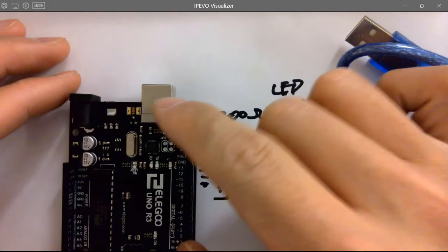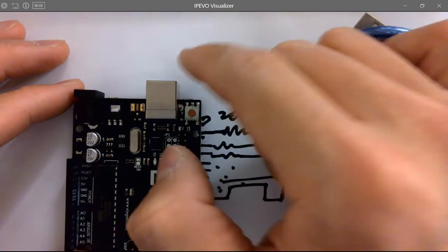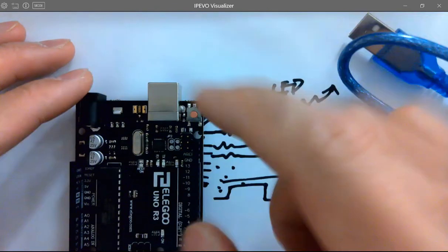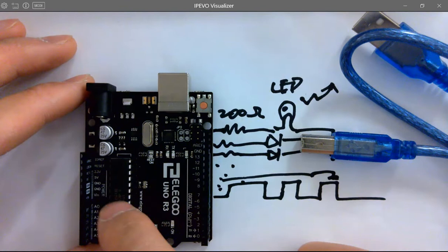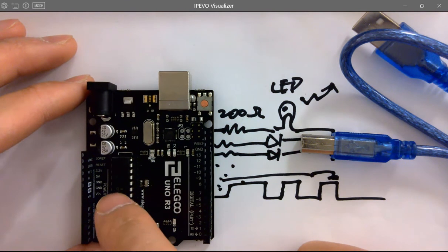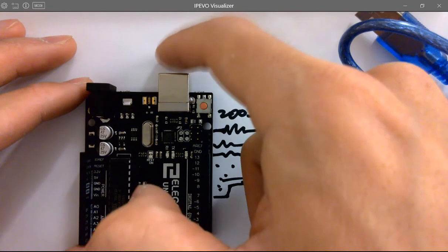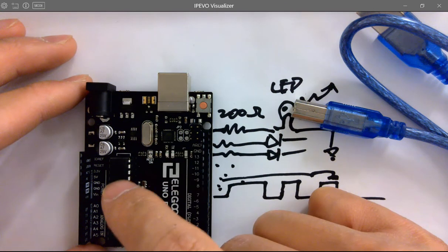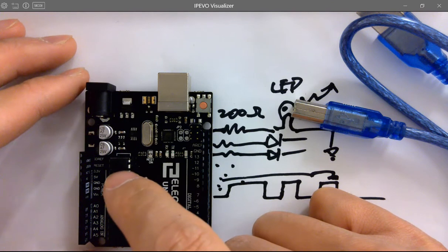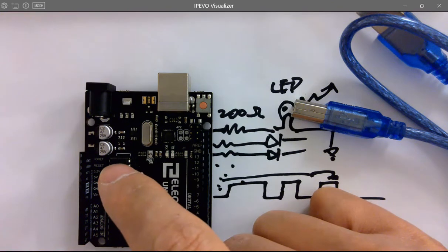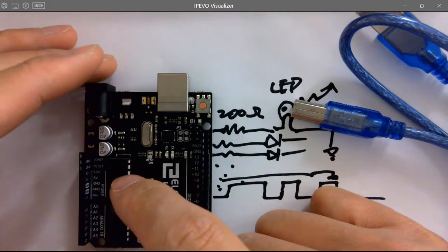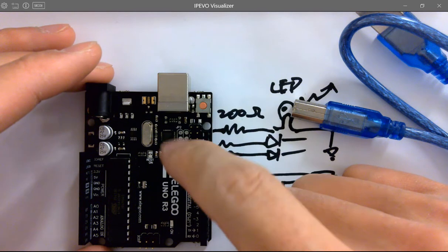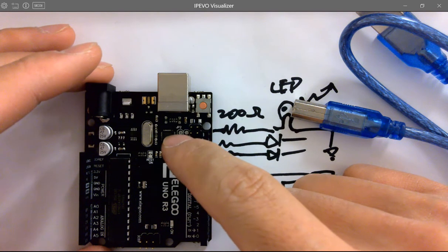And this is able to communicate with the computer, so you have your script written in the Arduino IDE and upload the code to the CPU here, or to the microcontroller over here. And it's being converted. So the USB protocol is being converted into UART. So we're going to learn UART in CE351, but now we just use it. We don't need to find out what's happening in UART. All right. So the USB data is being converted into UART by this chip, the USB to serial.